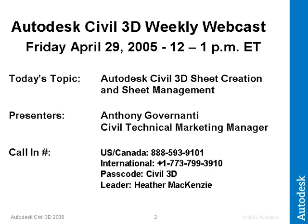Yes, hello. Hi, Anthony. How you doing? Nice show so far. All right, thank you. The classic example that I want to introduce is where you have a short cul-de-sac, and it makes sense to put two of them on one sheet in plan view and then in profile. And I understand the limitations of the view twist, but for aligning the two profiles, they're probably going to be in different parts of the model space. So I guess to cut to the chase here, my question is, the viewports that are produced by the map books are adjustable. You can unlock them, move around, pan around, and get the proper view that you want, correct?